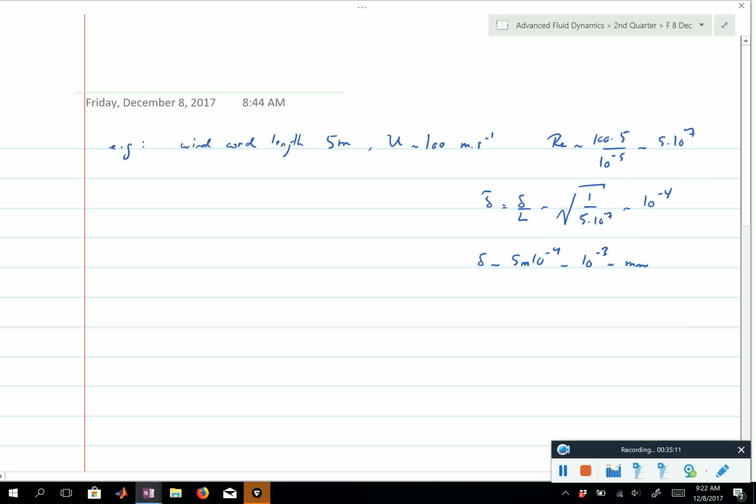And therefore, this is the only place where the assumption that the flow is irrotational is not valid. So this is where you have to look if you want to get to viscous stresses. When we were looking at an irrotational vortex, where is the vorticity? Well, it's actually in those small boundaries. So that's what a boundary layer is.